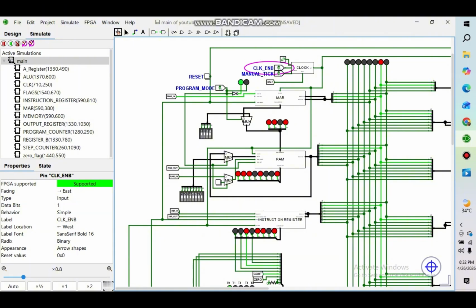In program 2, I changed the RAM values in program 1. The RAM values mean that 2F is load fetch, E0 is jump control instruction, 70 is ALU operation or store, 60 is end program, and F equals 1 is data stored at address F.